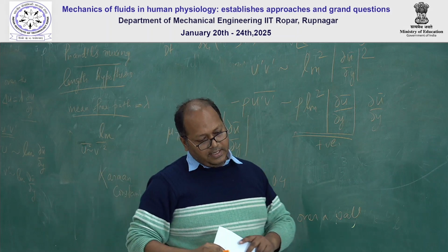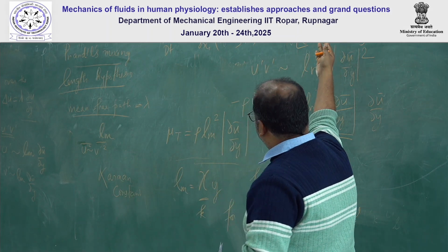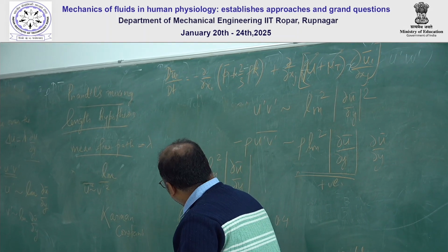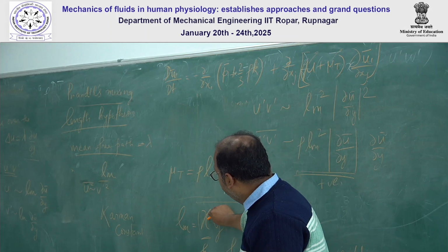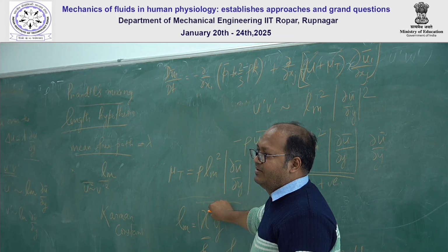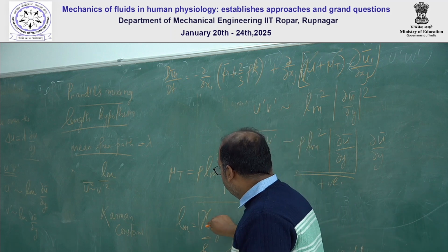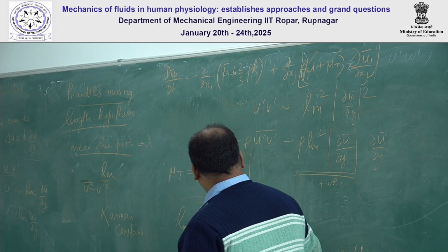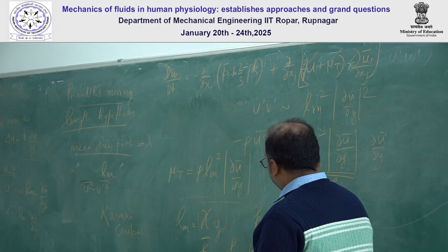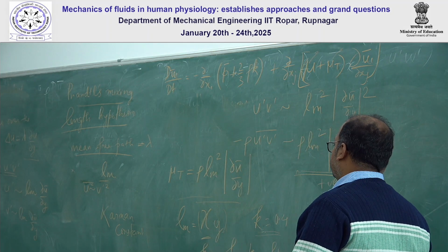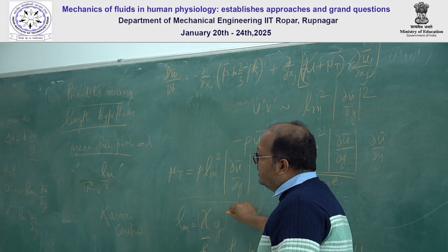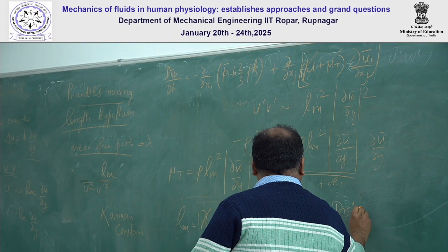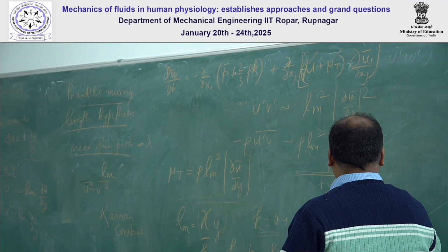Again, the turbulent viscosity itself varies from flow to flow. This is just valid for the flow over walls. This alphabet value will vary for different flow scenarios. For the flow over a wall or within a channel flow, we can keep this value as 0.4 of the y, and y is the orthogonal distance from the wall.